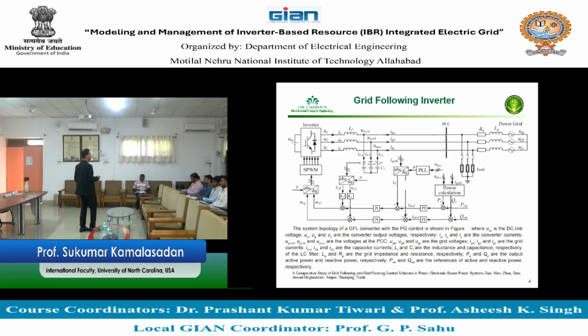Following? So that is done through converting from ABC to DQ. When you transform from ABC to DQ and control, you need this delta. That is the only way you can convert, from this delta or theta. You get it from looking at how the grid is operating. Okay.